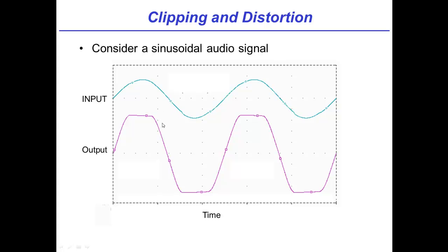Now, you would say that's a bad thing. The example we've used where the amplifier produces it, that's an example where your amplifier is clipping, and so when you turn your amplifier to really high volumes, it sounds terrible. But on the other hand, we can also use this in creative ways. For example, guitar effects pedals. Distortion and overdrive pedals that guitarists would use actually intentionally use clipping to create the distorted sound that we use, for example, in rock or hard rock guitars.